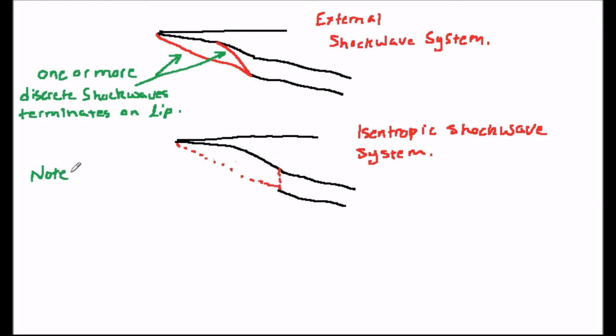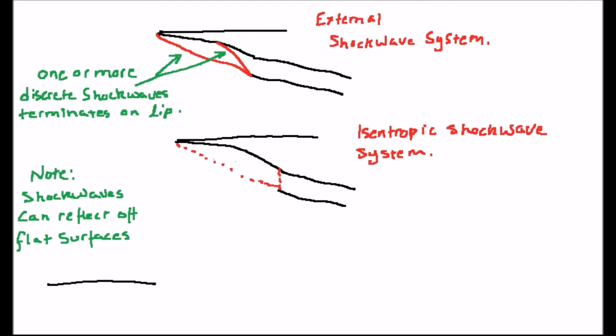The compression surface is designed so that the shockwaves terminate at the outer lip of the intake cowl without, hopefully, reflecting. As we will see later, the more shocks which are used, the more efficient is the intake. This system, however, results in long external compression surfaces.